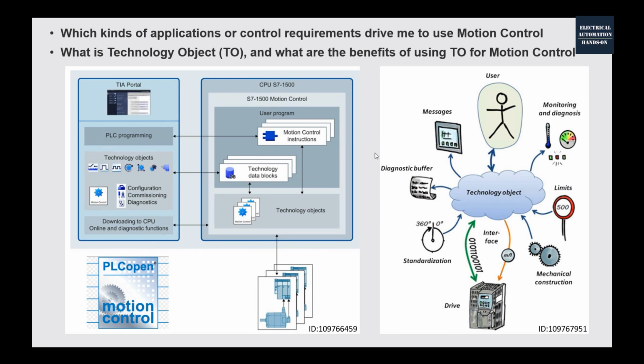If you recall, if you used the PLC to communicate with a VFD to do the speed control, for different brands of drive systems, for example, you are using the Siemens drive, or using the Beckhoff drive, or using the Allen Bradley PowerFlex drive, for different brands of drives, the communication or the data frame is not the same.